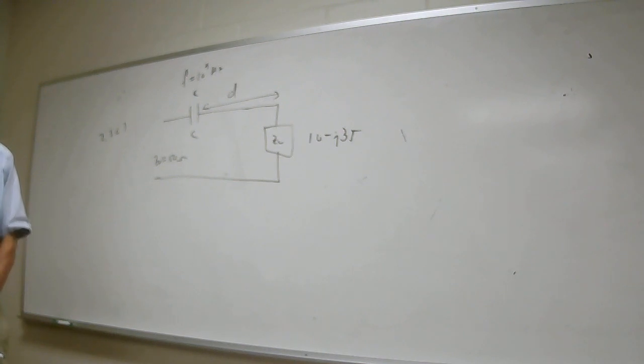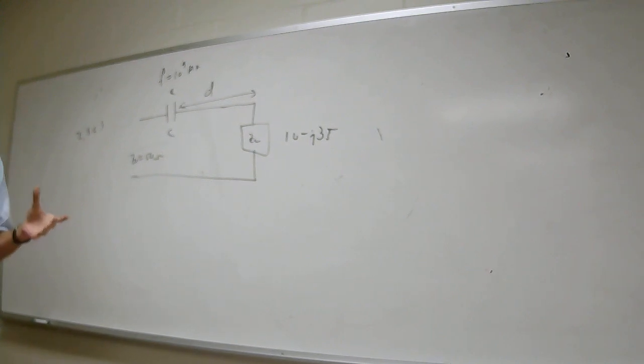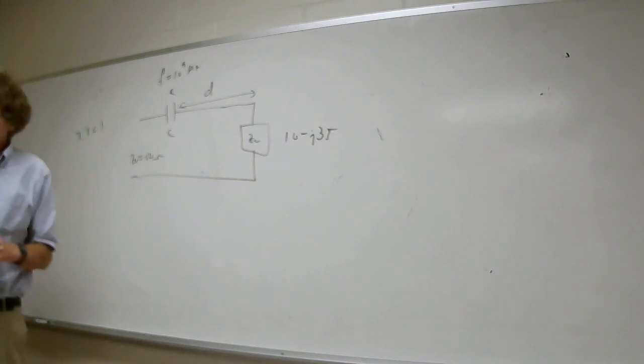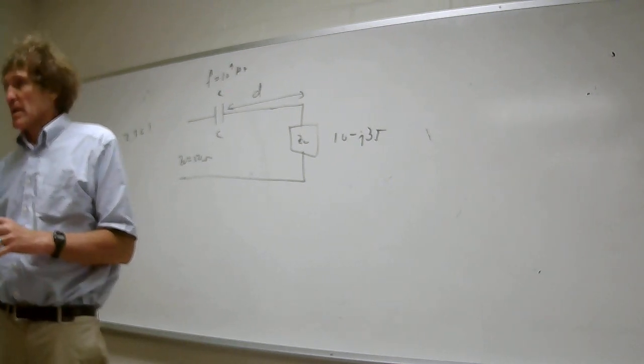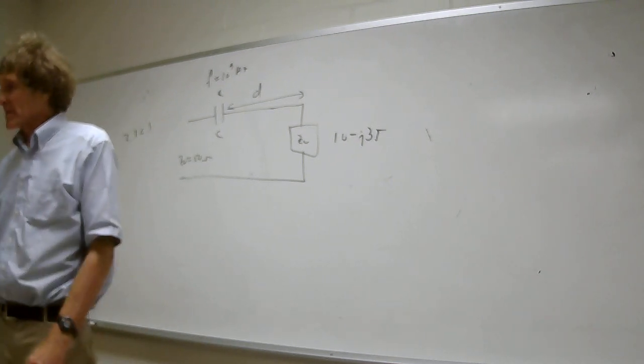So 0 times L is 0. The impedance of an inductor at DC is a short circuit. It's a piece of wire. You all follow me, class? So they usually want inductors in series and capacitors in parallel. The reason is DC biasing can be used if circuits are designed that way. Did you all have your analog electronics? Okay, then you don't know what I'm talking about.